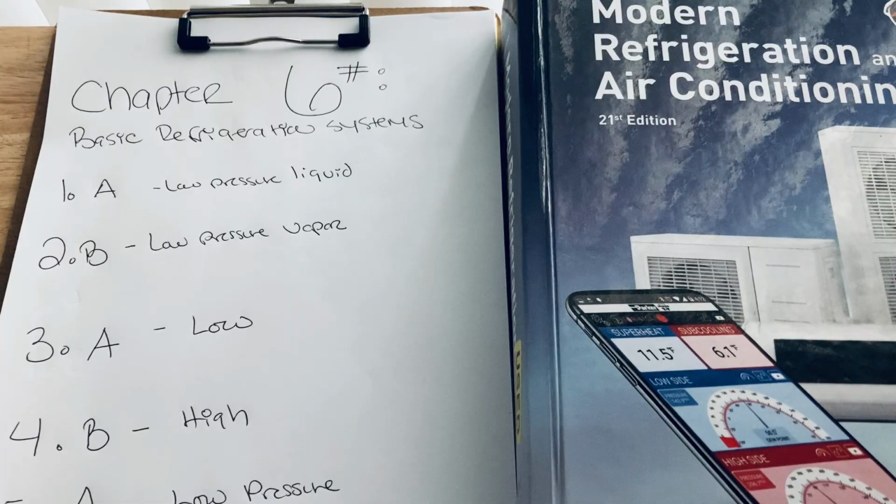Number 5, name the 2 types of air-cooled condensers and explain their advantages and disadvantages. So we just talked about that in the previous question. The first one is going to be, they're both on page 90. Forced air condenser, I put, has fan, removes heat more quickly, period. The second one is natural convection, which doesn't use the fan, but it cools by the flow of air, period.